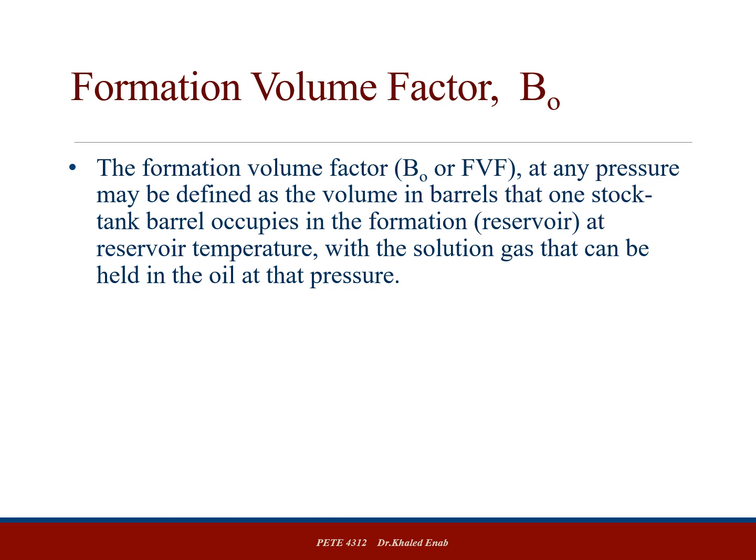The second property we'll cover today is the formation volume factor, known as Bo or FVF. Formation volume factor at any pressure may be defined as the volume in barrels that one stock tank barrel occupies in the formation reservoir at the reservoir temperature, with the solution gas that can be held in the oil at that pressure.